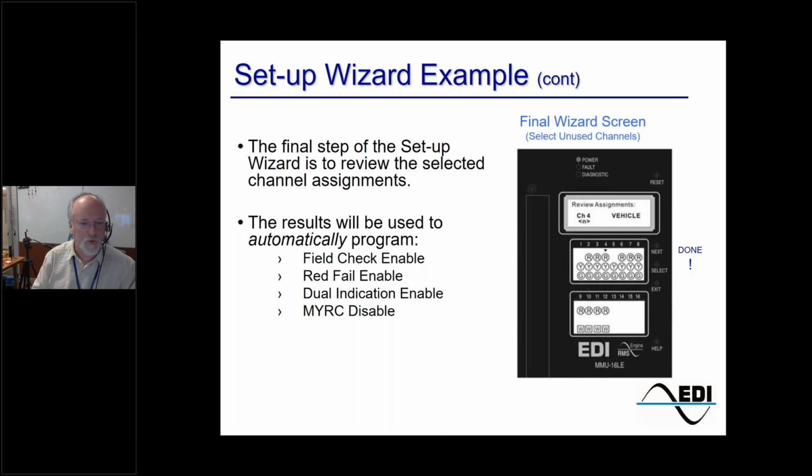Flashing yellow arrows, when you are setting up a new intersection, if it's a flashing yellow arrow intersection, tell the monitor that the unit has a flashing yellow arrow, tell it its mode and all that, then do the wizard. It's very important that you do the flashing yellow arrow wizard first before you do the setup wizard.